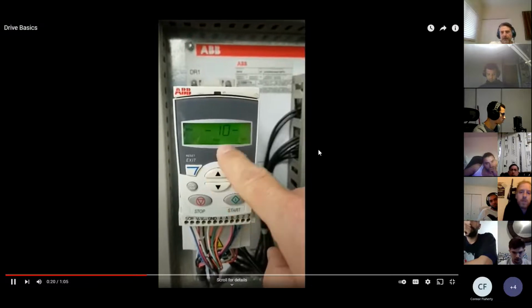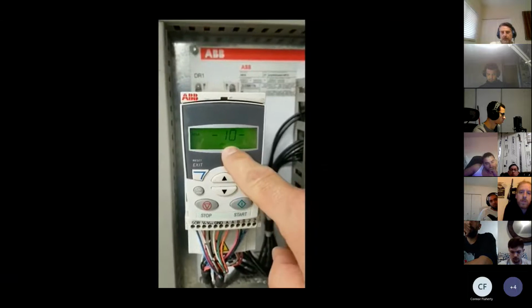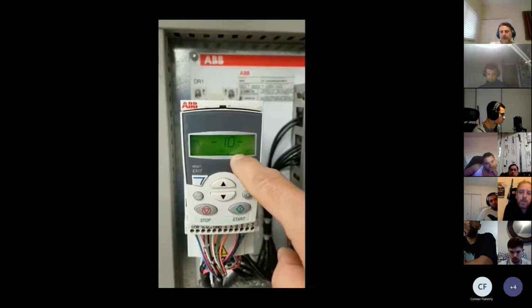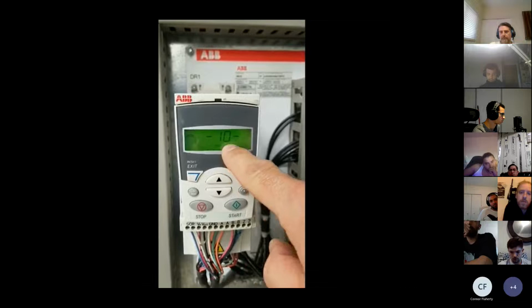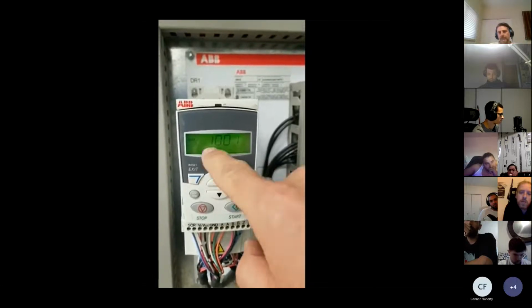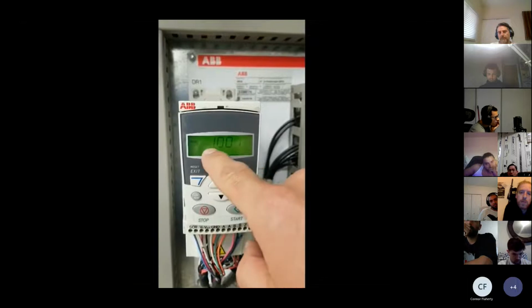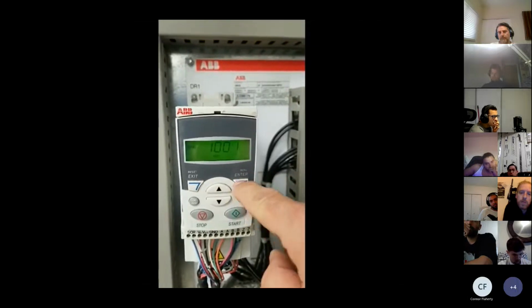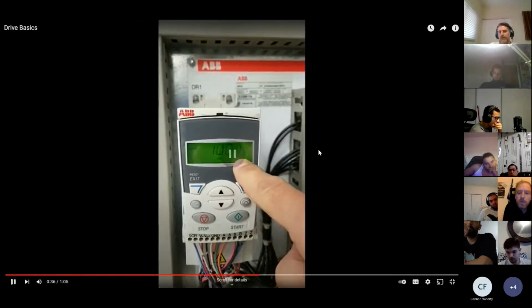One of the first ones we're going to discuss is 1001. To get to our parameter number as quickly as possible is only 2 digits here, but if I press enter, it'll display 4 digits. So right now in parameter 1001, if I press enter quickly, it'll give me what the value is. There was an 8 there. What's 8 for? It was programmed for 8.